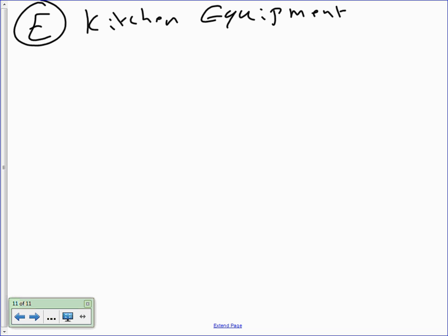There you go. Okay. For kitchen equipment, guys, you're going to go to 220.56 and the table. There's a table and there's an article, and it will tell you if you have more than 3, I believe. Did we say 3? More than 3, you cut it. Can you guys go to the table and see? I can't remember if it's more than 3 or 4. Go to 220.56, because that's a new table.